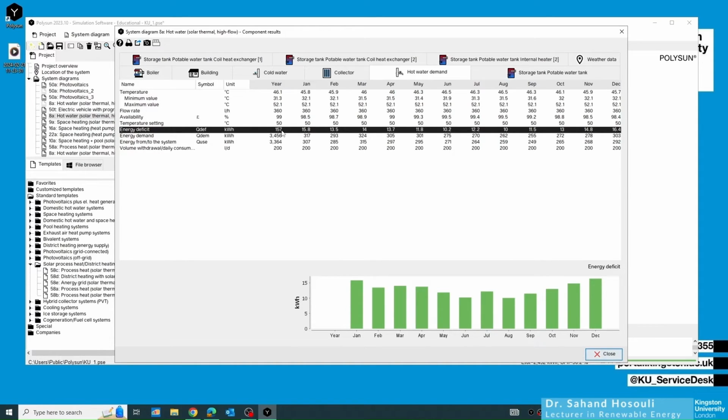In this case, because the energy deficit can't be compensated by the following time steps that are meeting the demand or higher, the deficit can't be reduced. So in terms of the energy deficit, it's going to be 7 plus 8, so 15 energy deficit. However, we can't include that 10 extra production in the second step. That's the reason why the energy deficit number doesn't match what we have here.